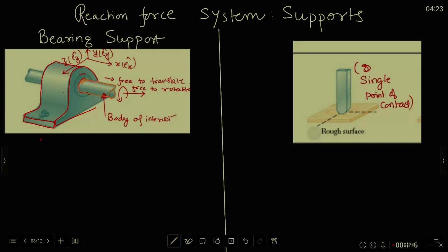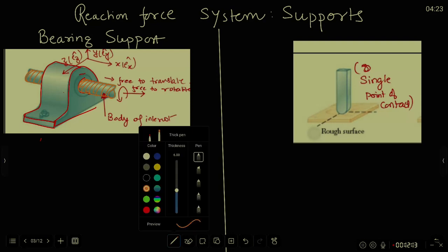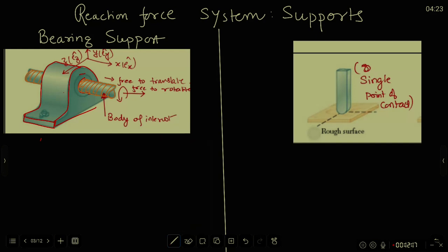Now the rod, and the bearing, they are interacting at multiple points, right? The interactive force must be a distributed force. I don't worry about that. I will just write the simple resultant, say at this point B. I'll draw the free body diagram of the rod.